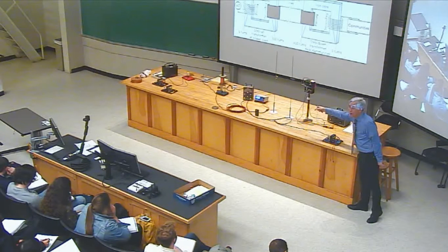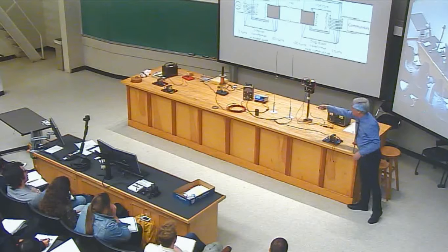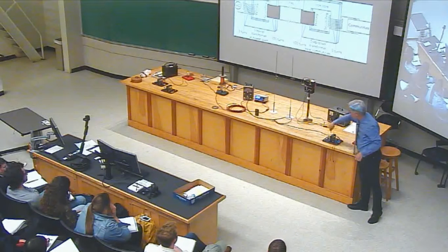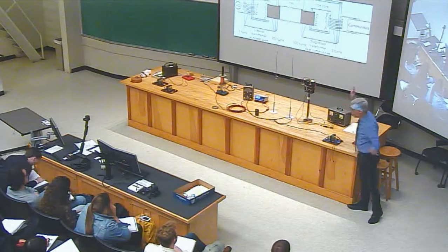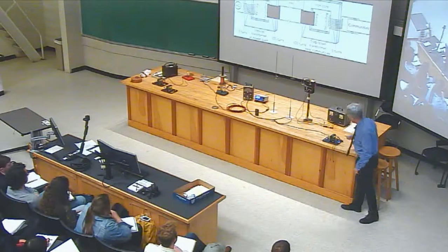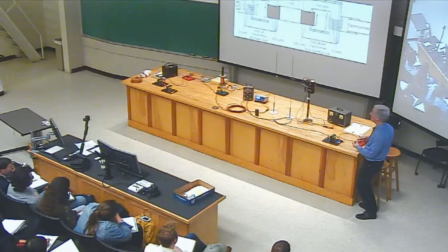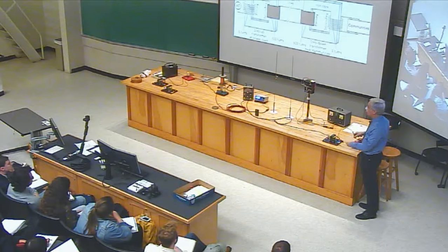These wires now are part of a middle circuit that connects to nothing else. It connects to the secondary of the step-up transformer, the primary of the step-down transformer, and nothing else. So the charges are trapped forever going around this little circuit. And finally, the step-down transformer's secondary will provide us with 12-volt, high current.